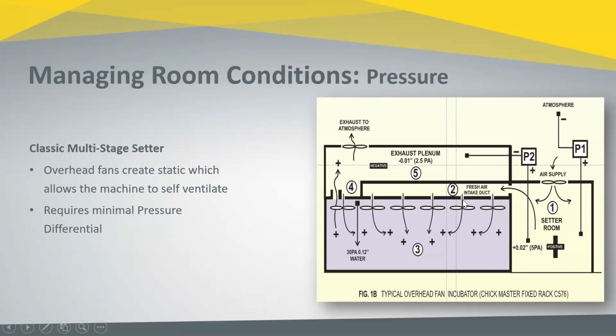So we recognize with a classic incubator, and I talk about it as a self-ventilating machine, because this machine could just be constructed in an open environment with no room pressure or no plenum pressure, just strictly a machine standalone. And by turning on the fans, that machine will draw air into the fresh air intake and will exhaust it out the exhaust ports due to that pressure differential created by the fans.